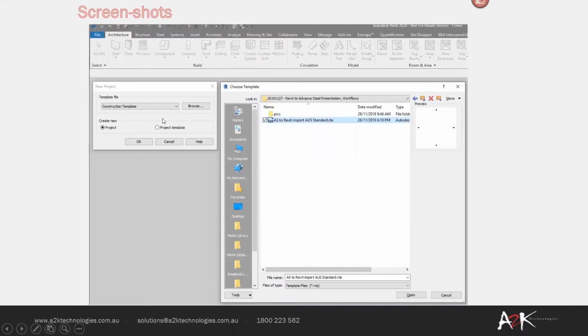So this is now where we will try and bring that into Revit itself. One of the things with it is you are always best to actually set up a template which contains all your steel families for mapping. So it does need to map the members. If you export from Advanced Steel, if you bring across a beam, it really needs to map that to